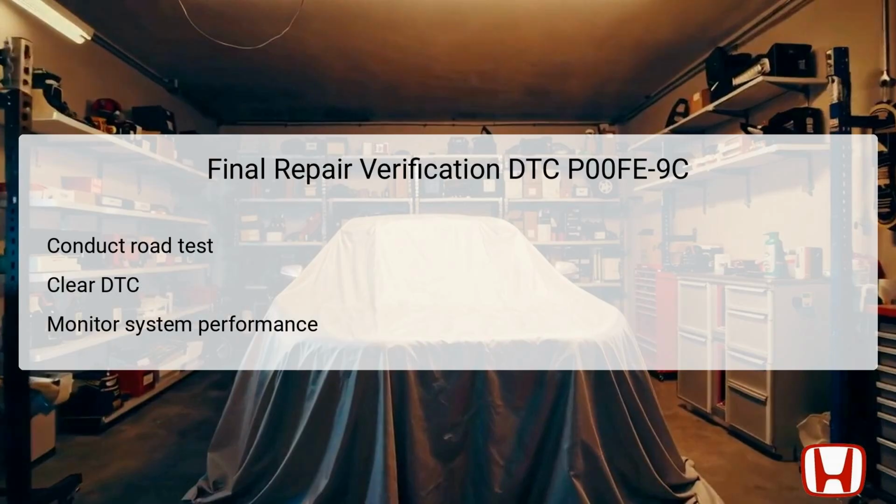Following the test, clear the DTC using the Honda Diagnostic System, HDS. This step resets the system, enabling a fresh start for the monitoring diagnostic operation. Once cleared, it's essential to monitor system performance over subsequent driving sessions.